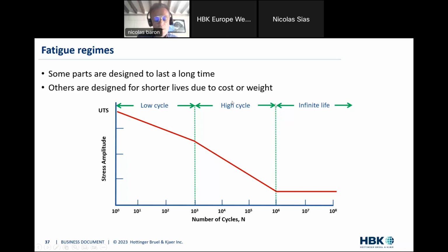And stress life, SN, works really well in this regime here. So whenever you have a high enough number of cycles before reaching failure, the SN methodology is appropriate.